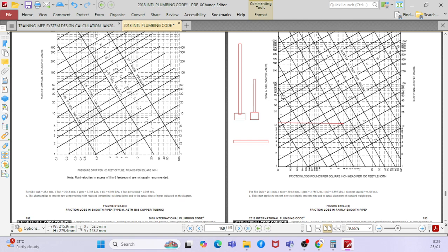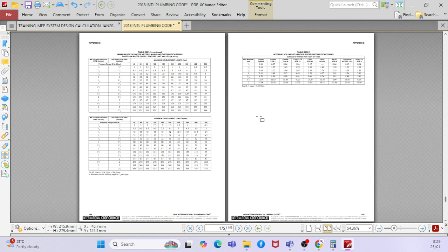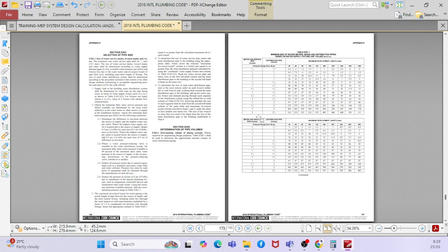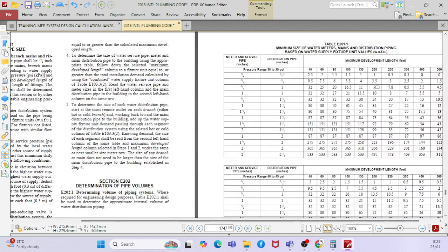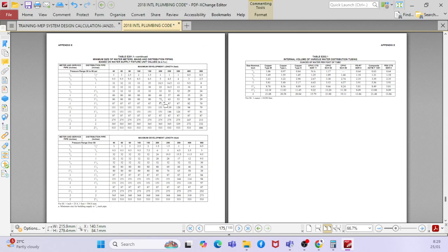Okay. So if you have a straight duct, straight pipe, an elbow, valves, you have to calculate properly all the fittings. So how do you calculate all the fittings? There is a table given here. If you go to this table, you can see the pressure drop for the different pipelines and for the different fittings.